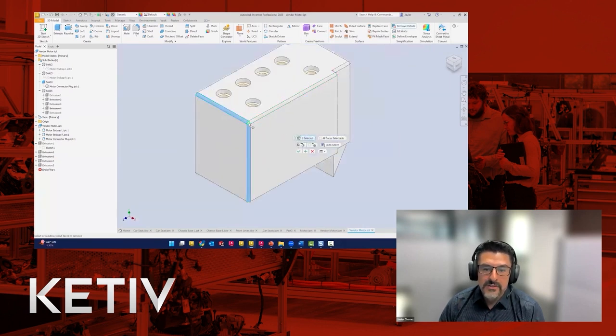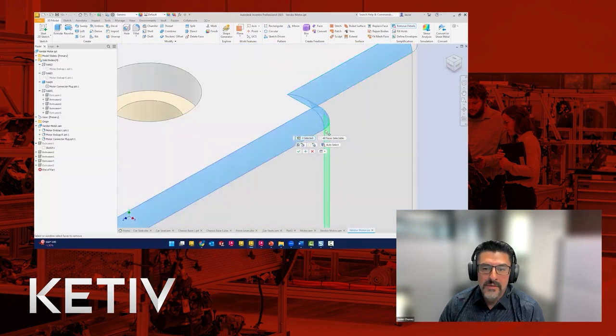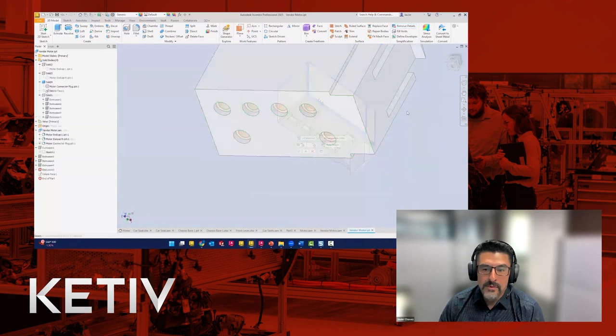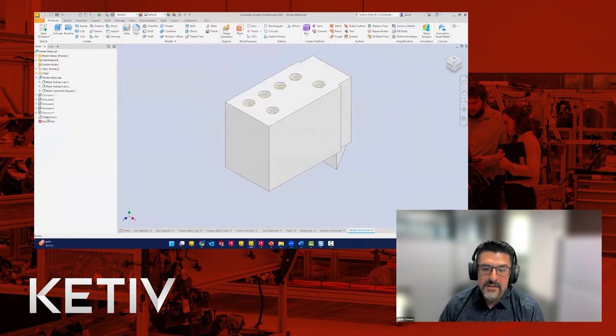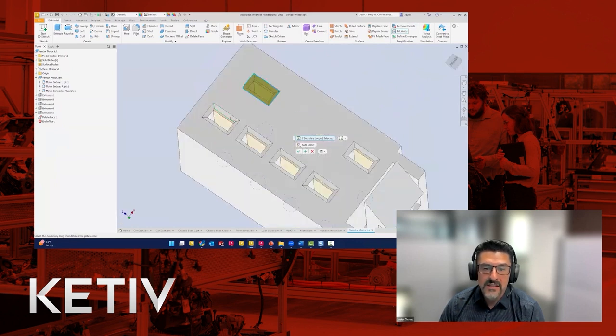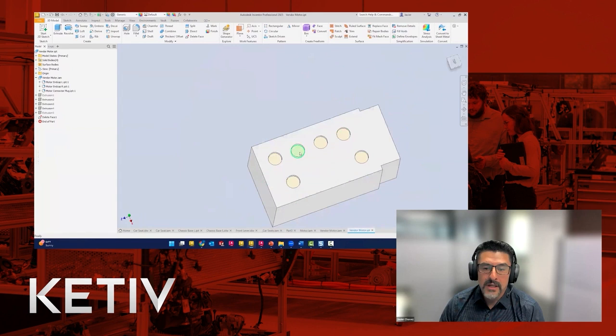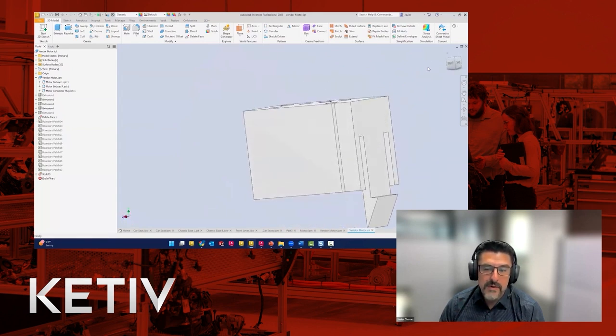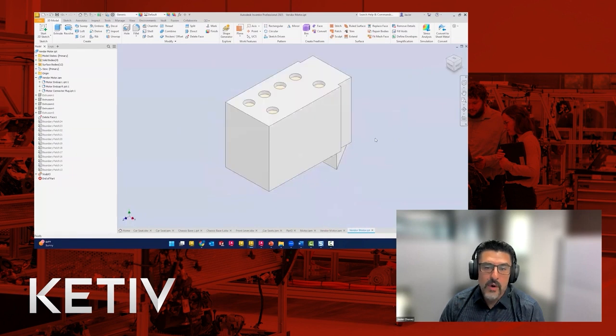And there's tools there just to remove edges, rounded off edges, and make this more squared off and simplify this. In addition, there's also tools to start eliminating voids. So there is a void inside of this with all kinds of detail. We don't need it. We're going to plug this up and sort of fill it up, if you will, as if there's nothing inside, just by plugging up the holes. And when you do that, we've got the most basic representation of this, and we still know where the wires go, right, on this.